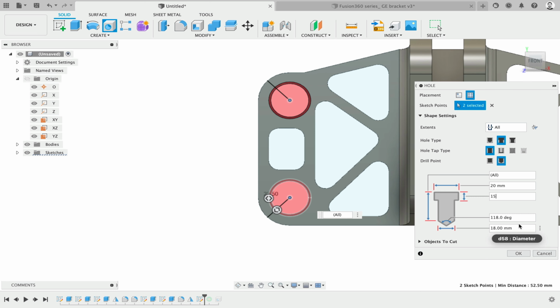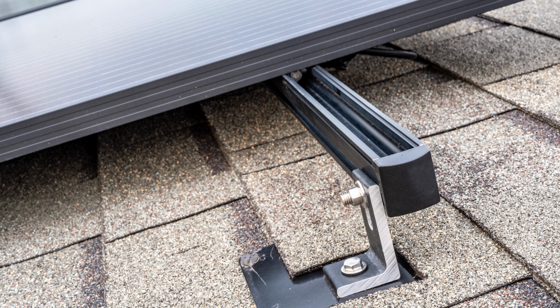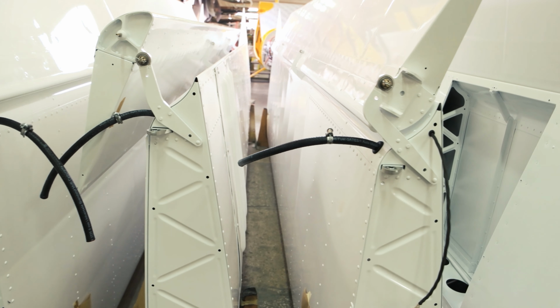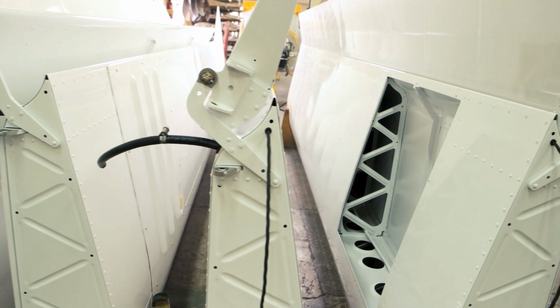Think about multifunctional components, so identify opportunities where a single part can serve multiple purposes. For example, a structural bracket might also serve as a mounting point for other components. Design parts that can be used in multiple products or configurations. This standardization reduces the variety of parts needed.